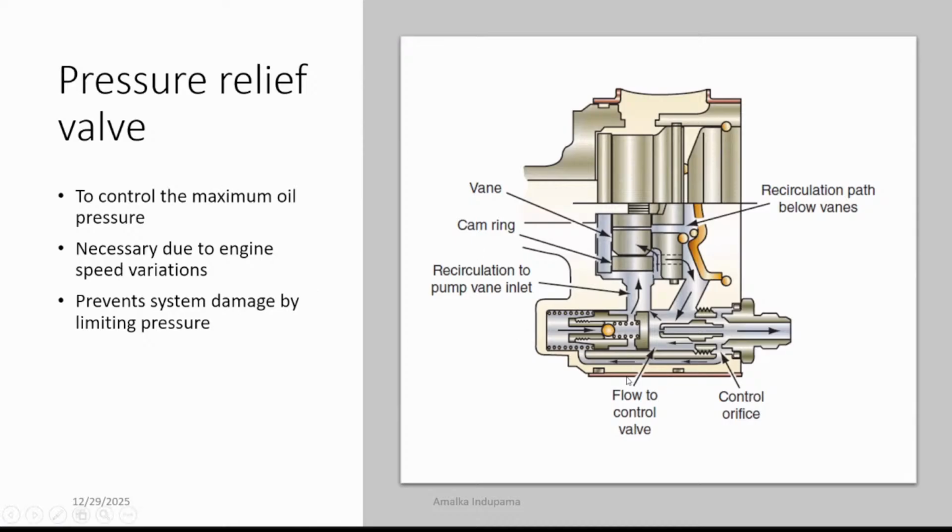The pressure relief valve is used to maintain the correct pressure inside the system, actually to avoid overpressure, because this power steering pump is driven by the engine crank.